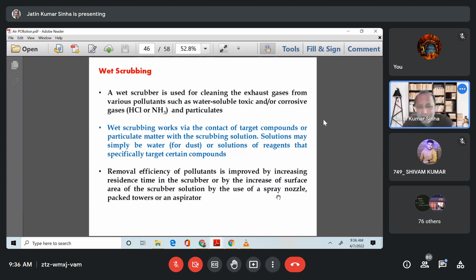If your pollutant is an acid, they expose it to some base material so that it reacts with the acid material and gets neutralized, and finally it is collected at the bottom of the system with water, and finally removed. Depending on the requirement, there are different types and designs of wet scrubbing systems, but these are very much limited to industrial scenarios, not domestic purposes.